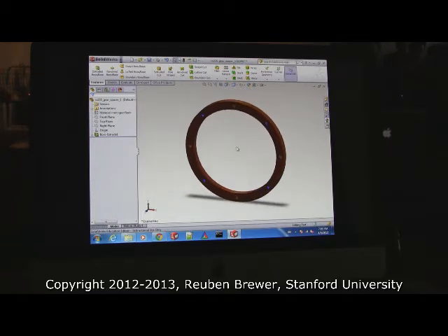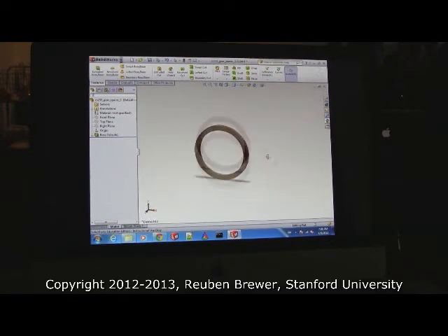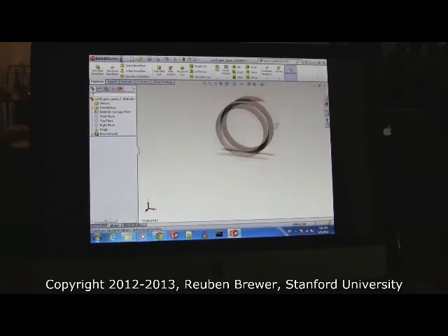Okay. Now go ahead and zoom way out. Oh, actually no, let's do this first. The way you translate is you hold down the middle scroll wheel like a button and the Control key at the same time. And then when you drag, it translates instead of rotates. So this is why CAD in SolidWorks is always two-handed. Your left hand does things like the Control and Shift keys and numbers, and your right hand does all the mouse stuff. So, can everyone translate?